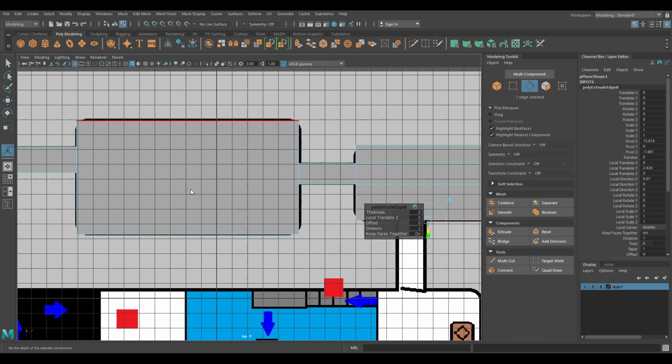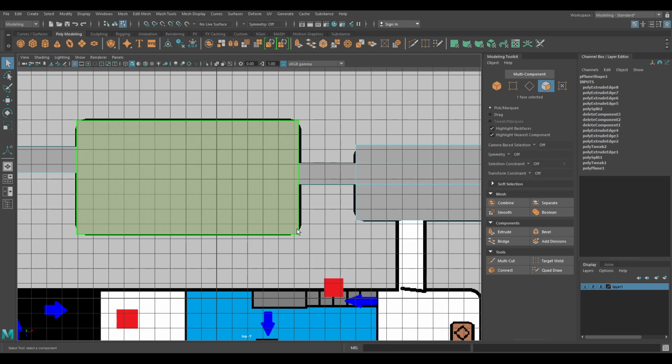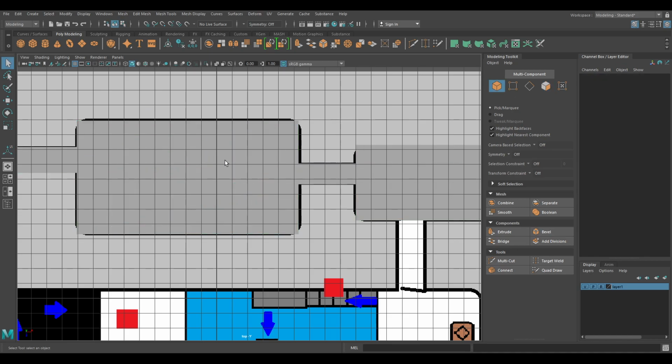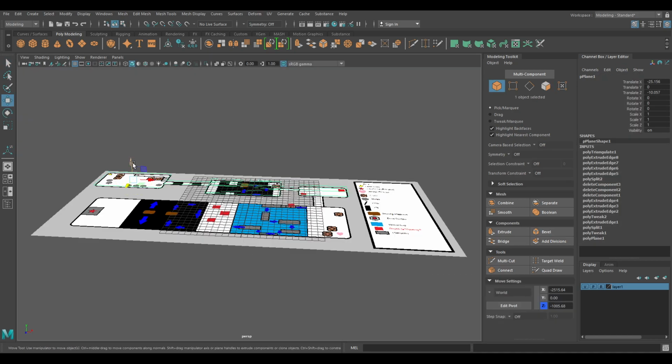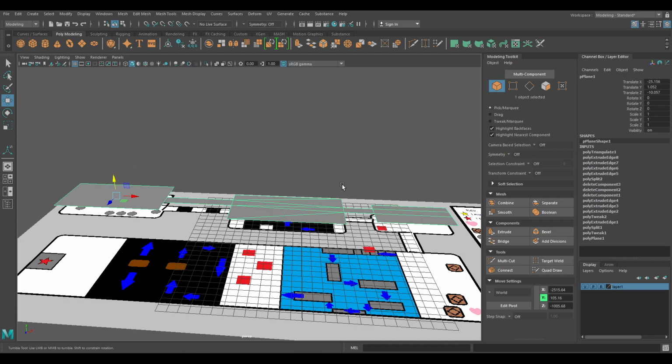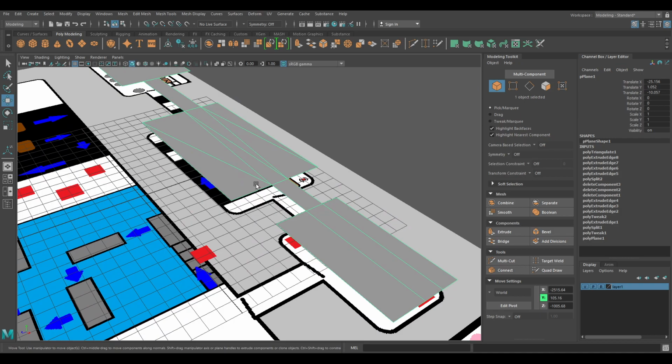Now, just so it doesn't behave weird in engine or anything like that, I could automatically cut this up myself. So I attach this to this, or I can just essentially select the face. I believe it's under mesh. So select that face, go mesh, click triangulate, and it'll just triangulate it for me. I'll just have a check on that. Seems okay. If I just lift it up so we can see it, that seems fine. I mean, it's not the cleanest geometry ever, but we're not really aiming for that. We're aiming for something completely different. So I'll just continue with this.